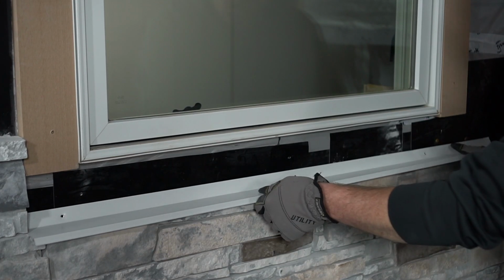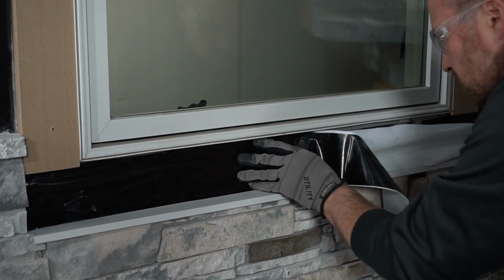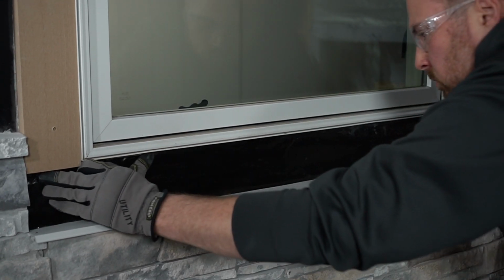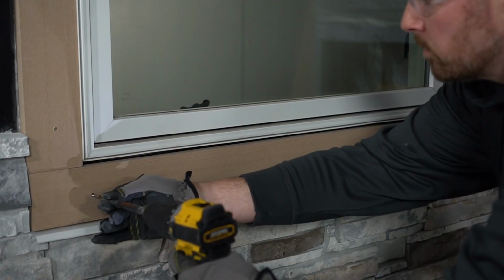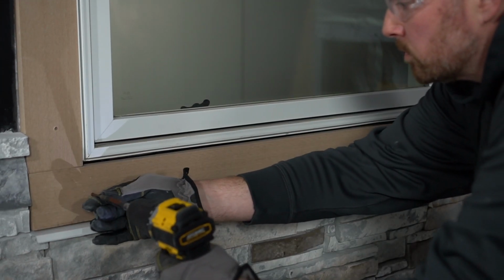If installing panels, install drip edge. Apply SAF over integrated flashing and drip edge of opening before replacing trim. Seal edges of trim and replace trim. No drip edge, fill 3/8" gap with backer rod and sealant.